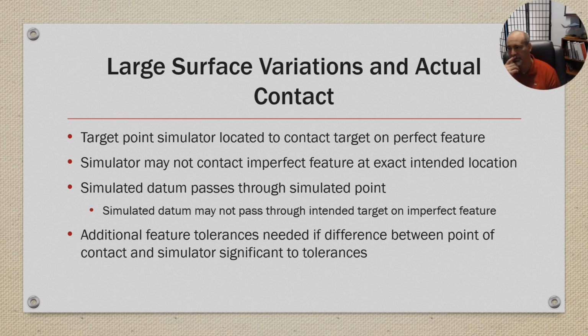tolerance. So this would be an example of I put something on my desk and try to use the desk as a surface plate. That's going to affect my measurement of anything I use, say, a height gauge. That's one reason we use precision ground inspection plates, so that we're trying to eliminate the tolerance of the simulated datum proxy, if you call it, from affecting our measurements.